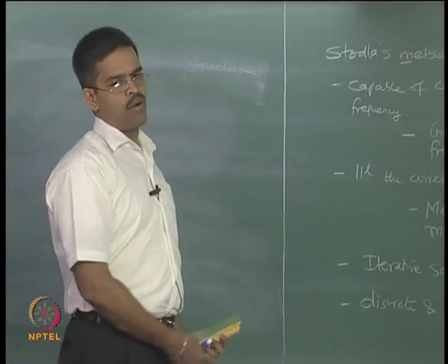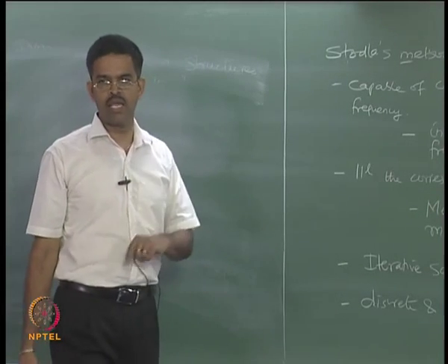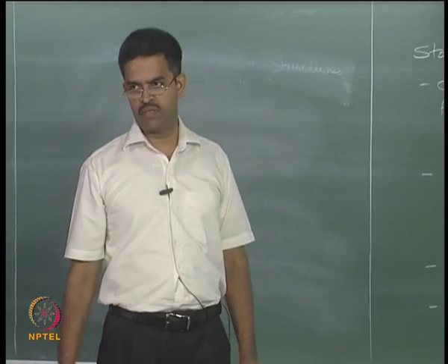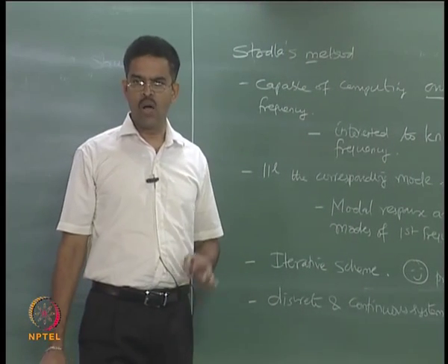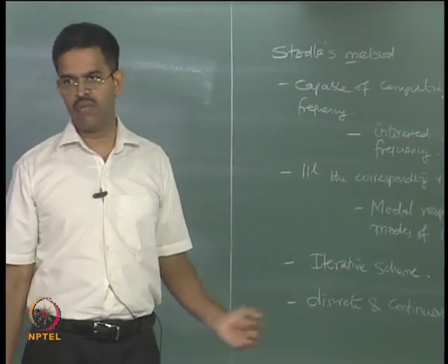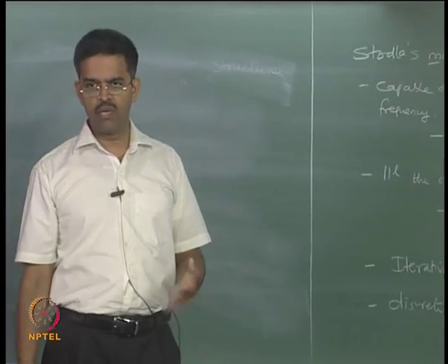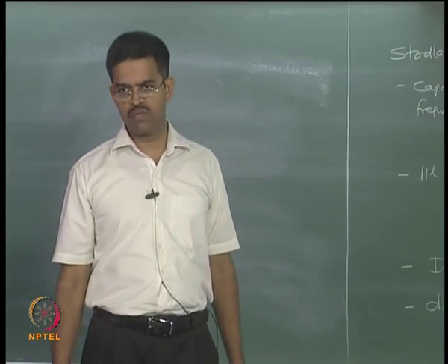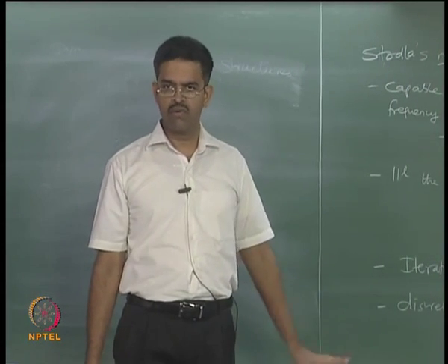And then solve the same problem using the classical eigensolver technique, because for solving it that way you need K and M, you do not need the alpha matrix. So you must know how to find the K matrix from the alpha matrix. The difficulty in all multi-degree freedom system exercises is how to mathematically model the system and how to find the first step of omega and phi for a given system, because to start the problem you must know the dynamic characteristics of the system. Free vibration response is a very important and vital landmark estimate of any MDOF system. Therefore I must at least know how to estimate MDOF system characteristics for the given problem.